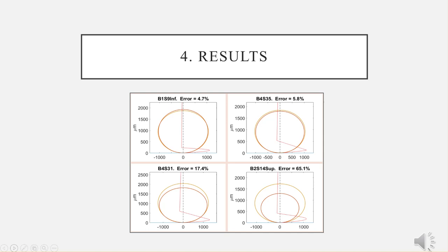As can be observed in the figures, most of the simulations allowed for a very good correlation between the elliptical bright region observed experimentally and the numerically simulated crack in the embedded to superficial transition. While most of the cases provided very little errors, 2 of the simulations could not be completely matched, resulting in graphs like the bottom right-hand sided one. However, even in these situations where the size of the ellipse is not exactly captured, the general tendency, particularly the aspect ratio, is still comparable.